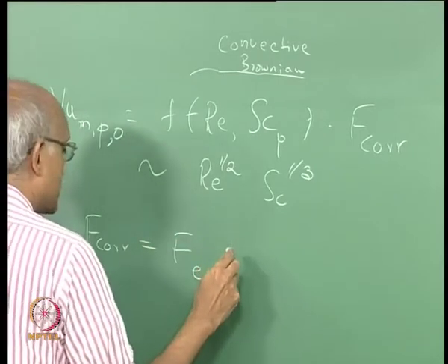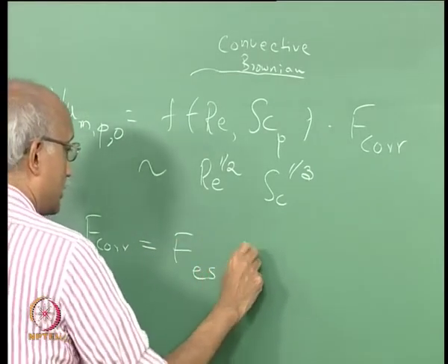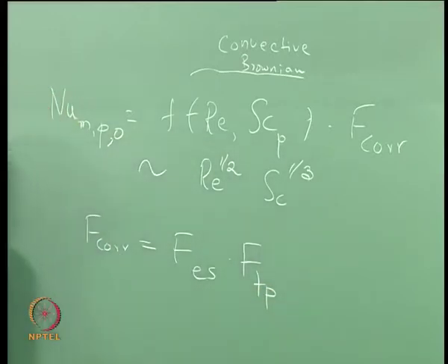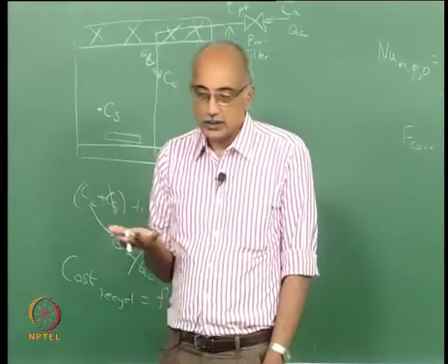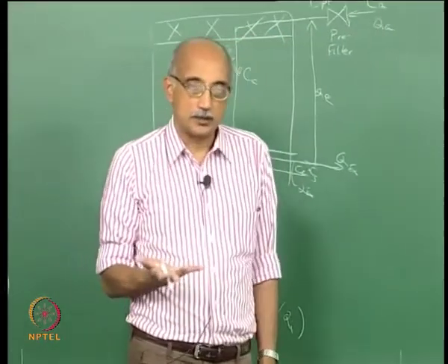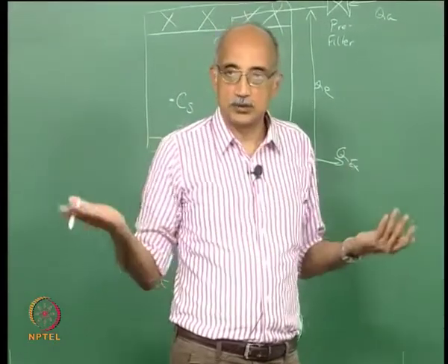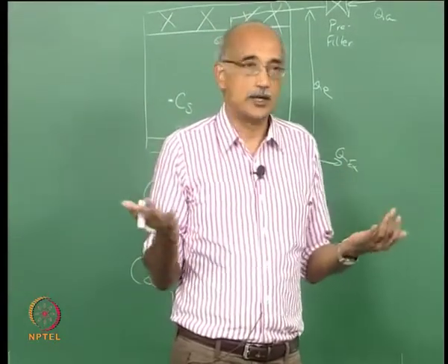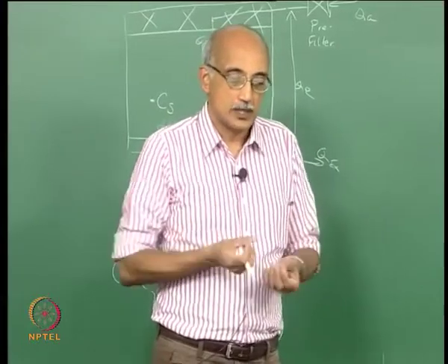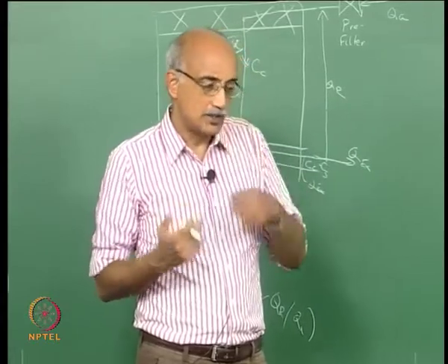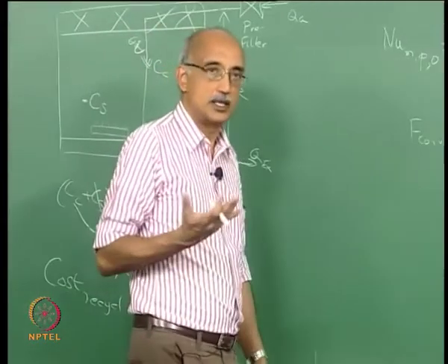and it will also have a correction factor due to thermophoretic forces, because again in a clean room the wafers, the product that's being worked on, will tend to be at a slightly elevated temperature compared to the facility away from the product, just because there are people nearby, there are tools doing operations, all of that in addition to generating mass also generates heat.